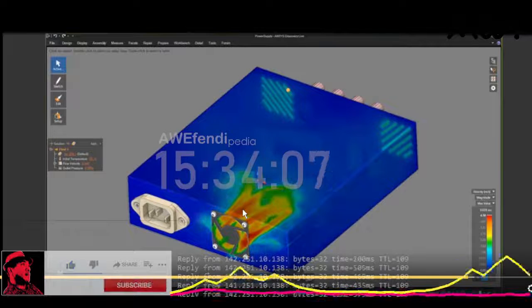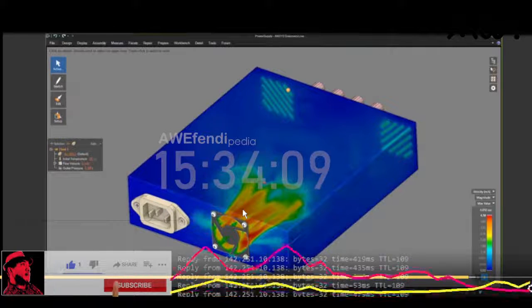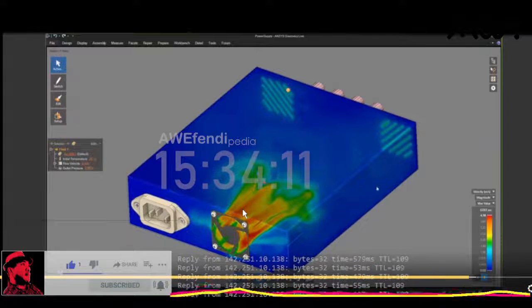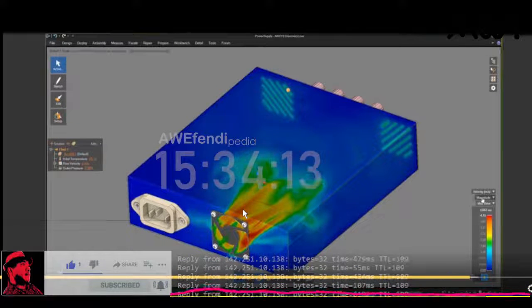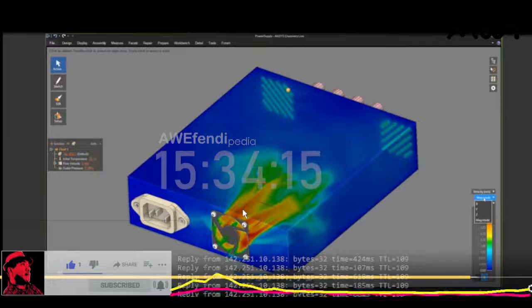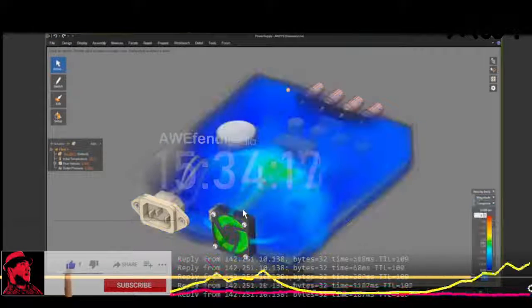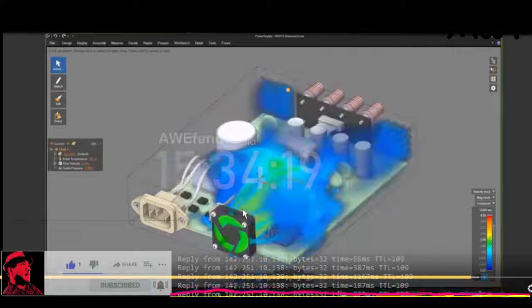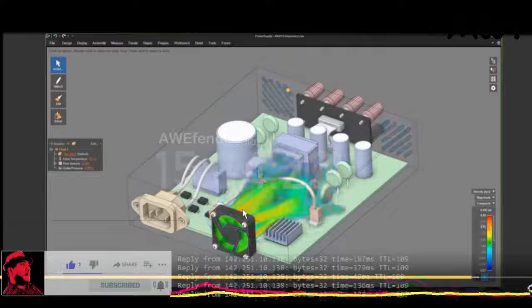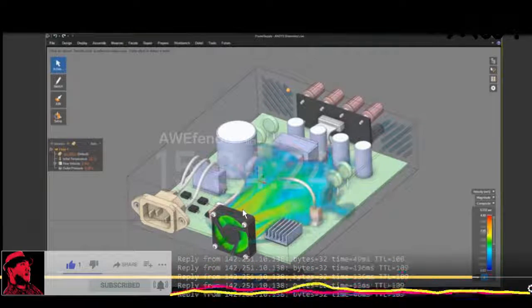So you can see here in a matter of seconds, I'm looking at the velocity as it's going through here. Now this display doesn't show us the inside. So let me go ahead and make some changes here. We can change the kind of rendering here. Something like composite might be super helpful to see, where I can concentrate on where I have those higher velocities, for example.